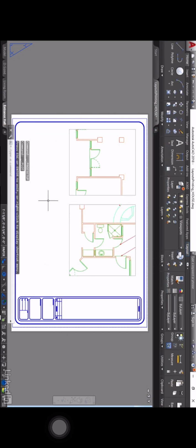So as you can see, when you're preparing your drawings to print or plot them, ideally you want to be using your Page Setup Manager. I'm not going to plot anything for you because there's nothing more boring than watching AutoCAD plotting drawings. The idea is to make sure that the page setup is set up effectively so that you can then apply it to other layout tabs in your AutoCAD drawings when you're plotting and printing to communicate your design intent.